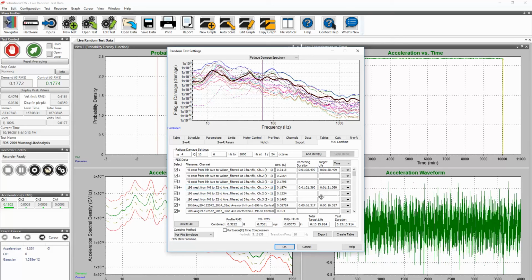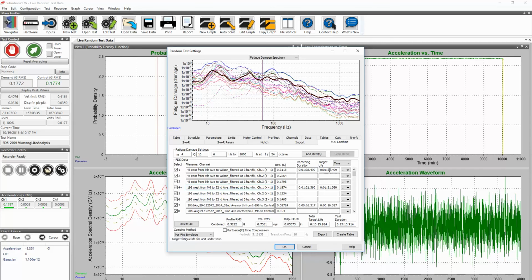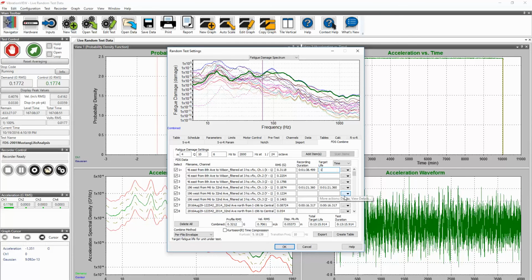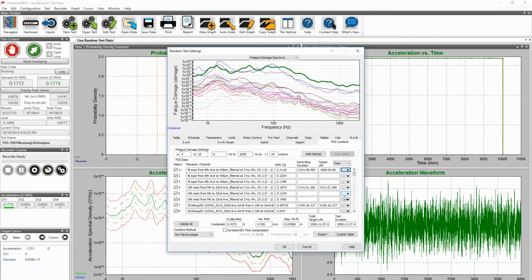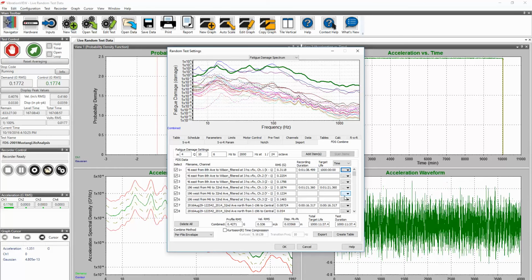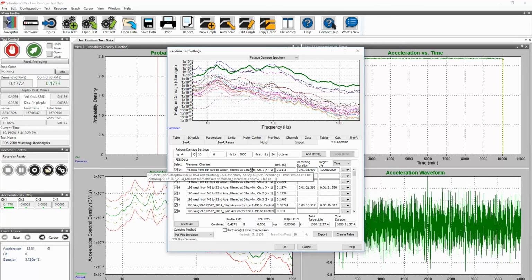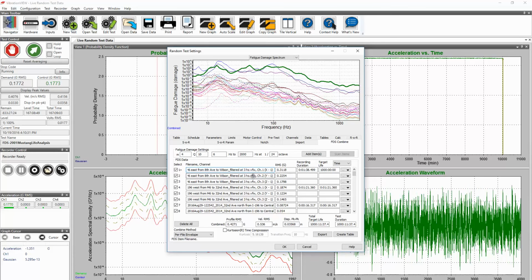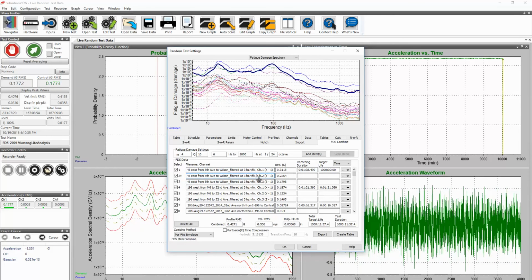That's because it automatically made recording duration and target life the same. Now, the target life we really want to put in, maybe it sees the first condition for 1,000 hours, so I can put 1,000 H, hit the tab, and it puts in 1,000 hours. If the target life really is that for this first situation, look what it did. It cranks it way up here. You can see that each one is significantly higher now.